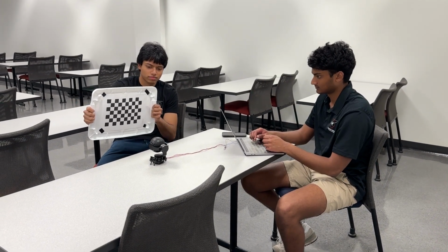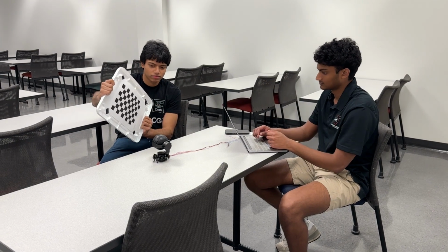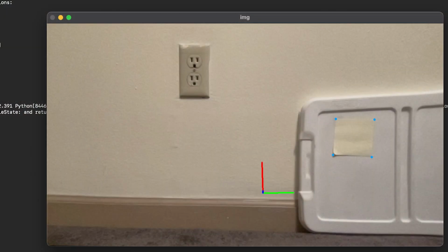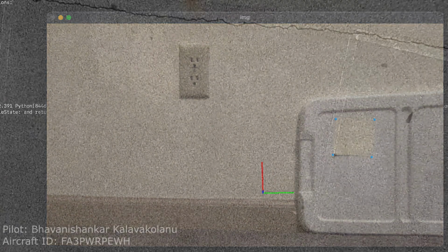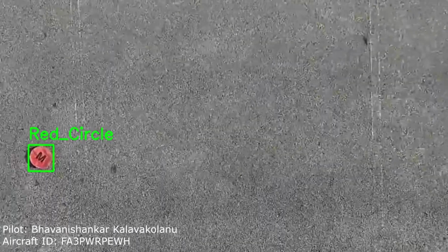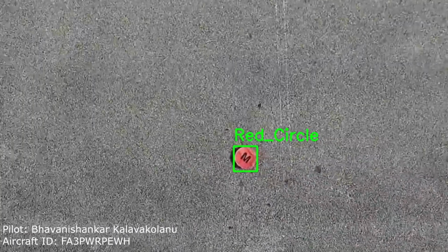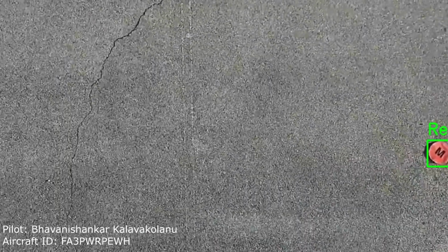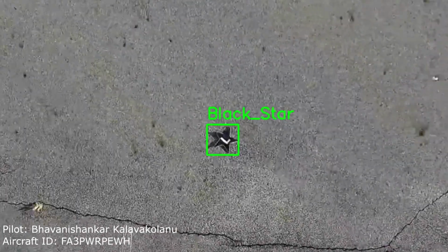The team employed a sophisticated algorithm for precisely locating the position of a vision target in the 3-dimensional space relative to the camera. By capturing images of a known calibration pattern from various angles, the team was able to obtain intrinsic camera parameters and distortion coefficients, ensuring accurate image rectification. Subsequently, a direct linear transformation was applied to find the position of the target relative to the camera position. From 24 meters in the air, the team was able to get on average 5 centimeters of error in their localization.